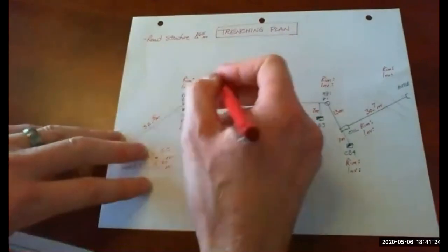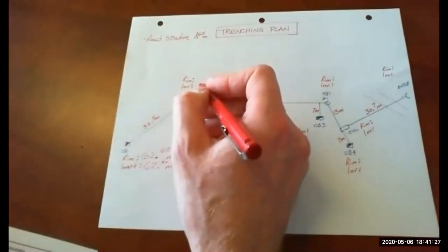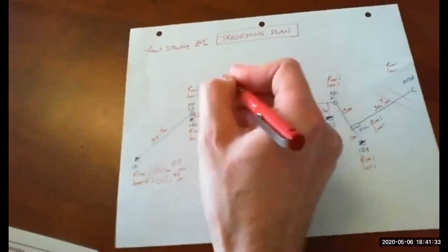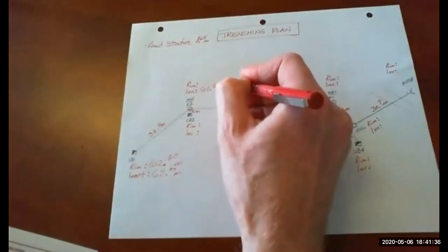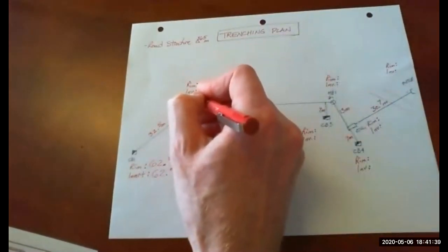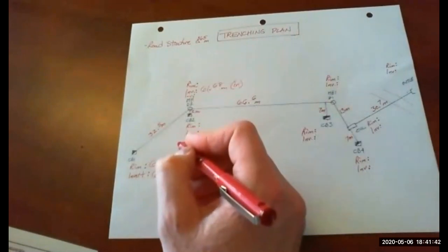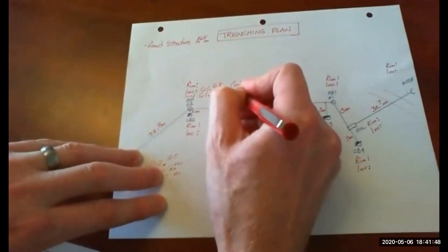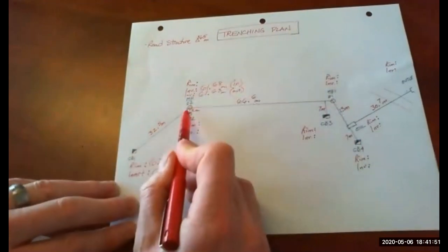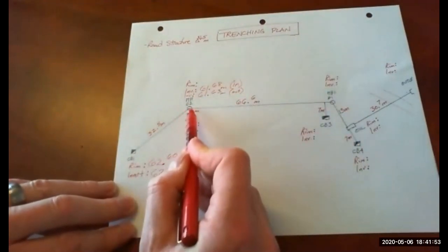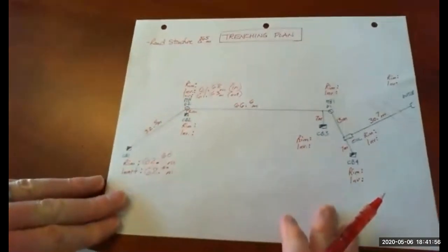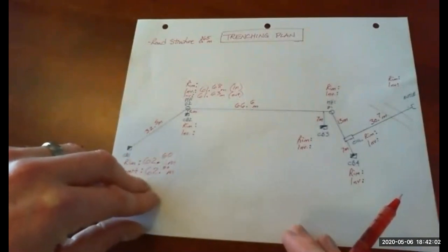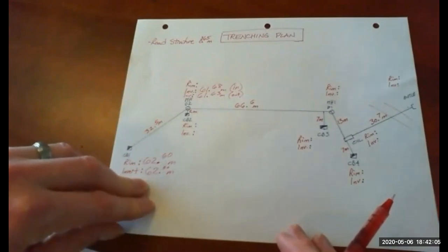Maybe I'll show both of those. So in is 61.68. So 61.68 meters. That's the in pipe. And the out pipe is 61.63. That's out. So in meaning on the inlet side of the manhole, and out meaning on the outlet side of the manhole. Once I'm done with these sketches, I'll scan them and upload them to Learning Hub so that you have them.